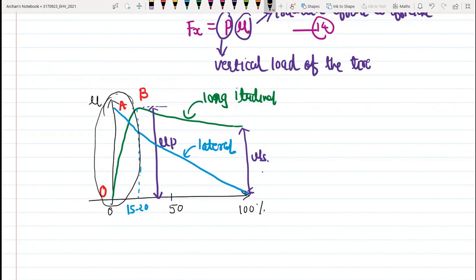Then if we further increase the wheel torque, a further increase in wheel torque and tractive force will result in a part of the tire tread sliding on the ground. Under these circumstances, the relationship between the tractive force and the slip is going to be nonlinear, and this corresponds to section AB.